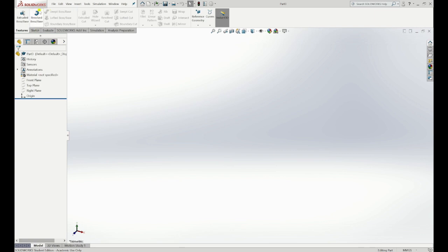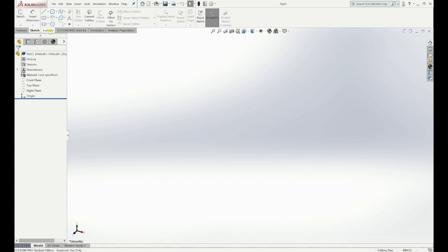On the top, you have a lot of commands. Some are hidden, some are visible. What SolidWorks tries to do is to simplify the amount of commands that are available to what you can do at the moment. I cannot do any of this until I have a part. But to do a part, I have to start with extrudes or revolves. But before I extrude or revolve, I have to do some sketching. Sketching is done here. These tabs only select the amount of commands that you have.